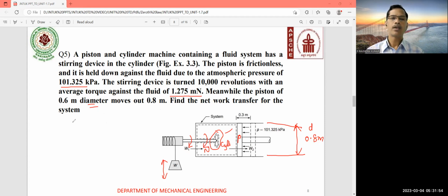That work we have already covered, that work is equal to 2 pi NT divided by 60. Sometimes, the thing you have to observe is whether you are calculating in kilojoule or kilojoule per second, that is in watts. Most of the time, power is in watts and work is in kilojoule. If you divide by 60, then you will get power.